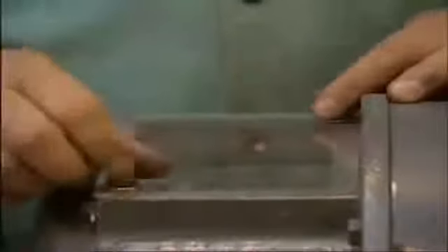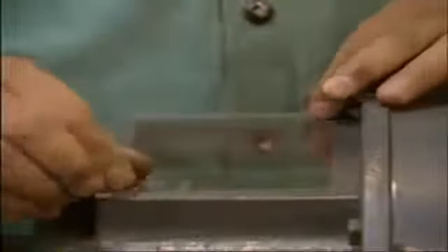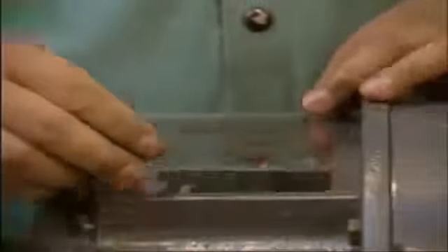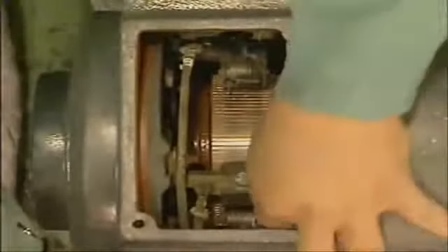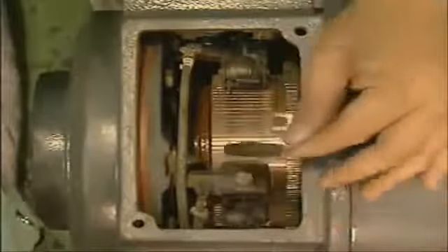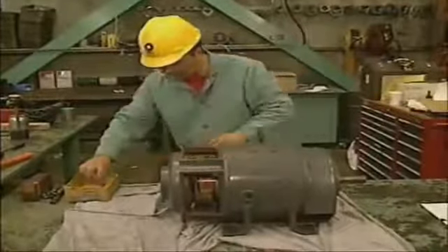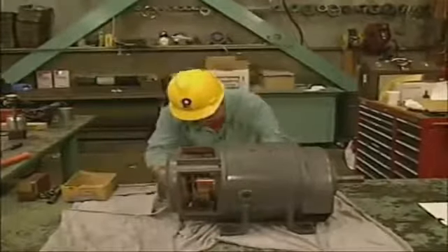The first step in disassembling a DC motor is to lift up or completely remove the inspection covers on the motor end bell to gain access to the brush rigging. Next, the pigtail bolts are loosened, and then the pigtails are slipped out of the bolts. The brush tensioning assemblies are then released, and the brushes are removed. As they're removed, it's a good idea to place them in a separate container to protect them from damage.